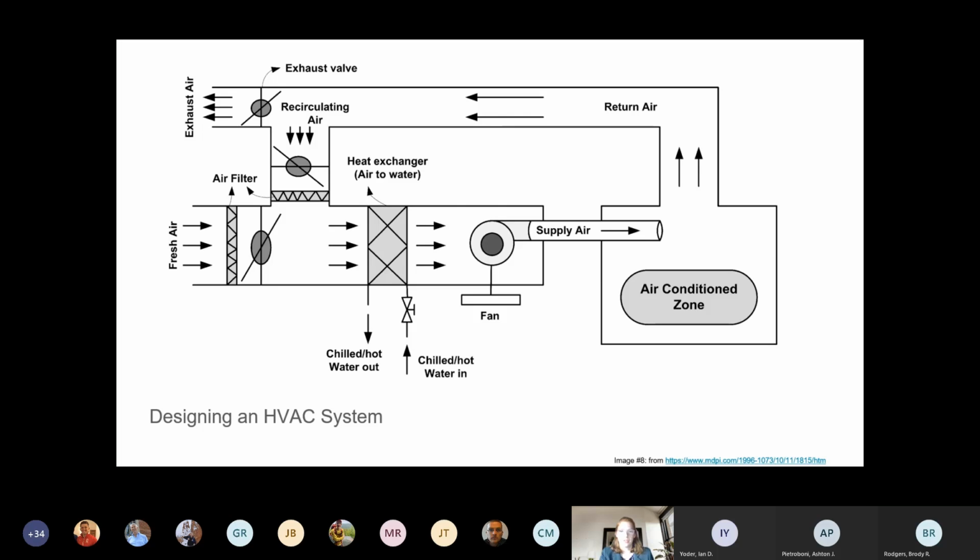Ordinarily, there are 3 temperature sensors in a single system: at the inlet, at the cooling coil, and the thermostat itself. To make way for fresh air, air in the zone is returned to the air handling unit. Depending on the requirements for the zone, a portion of the returned air can be recirculated and mixed with fresh air. This increases our system's efficiency because that returned air is already at the required conditions. If it cannot be recirculated, the air is exhausted.